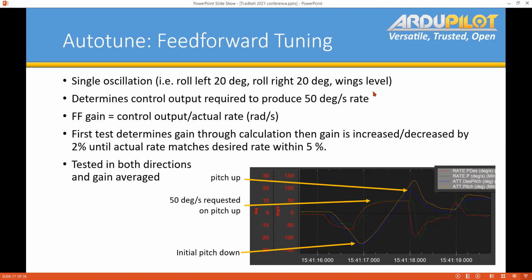We've got a PR in progress at the moment that looks like it's going to improve the limit cycle protection with tuning P and D on PIDs. It doesn't take away the risk completely, but it makes it a less scary place to go.